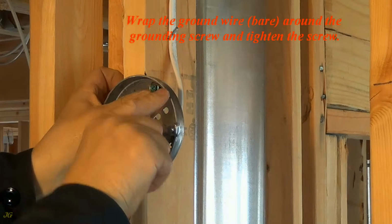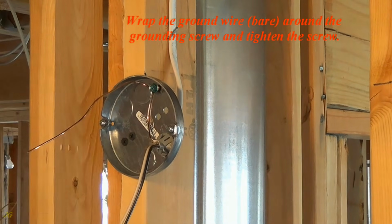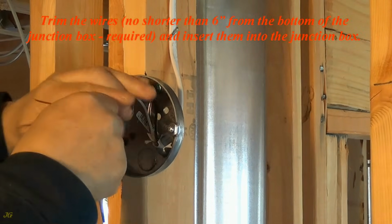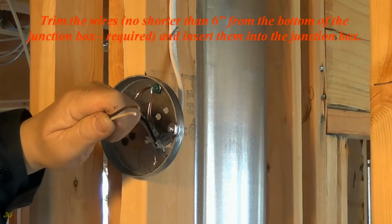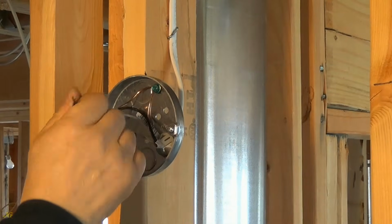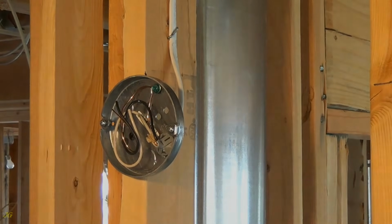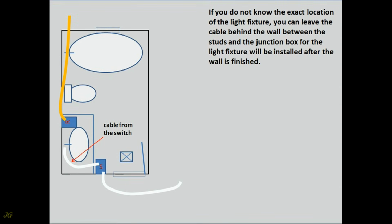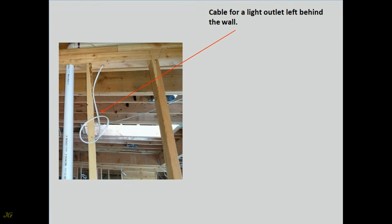Wrap the ground wire, bare, around the grounding screw and tighten the screw. Trim the wires, no shorter than 6 inches from the bottom of the junction box, required, and insert them into the junction box. If you do not know the exact location of the light fixture, you can leave the cable behind the wall between the studs, and the junction box for the light fixture will be installed after the wall is finished. Cable for a light outlet left behind the wall.